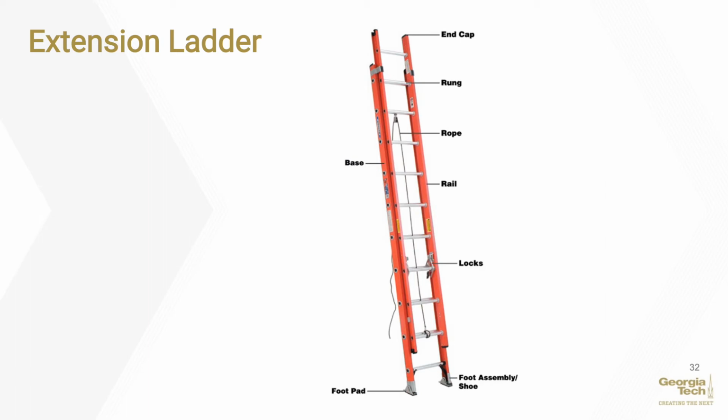Do not exceed the maximum intended load of a ladder or the manufacturer's rated capacity. Use ladders only for the purpose for which they were designed. Angle non-self-supporting ladders so the horizontal distance from the top support to the foot of the ladder is 1/4 the working length of the ladder. Job-made wooden ladders should have an angle that equals about 1/8 the working length.